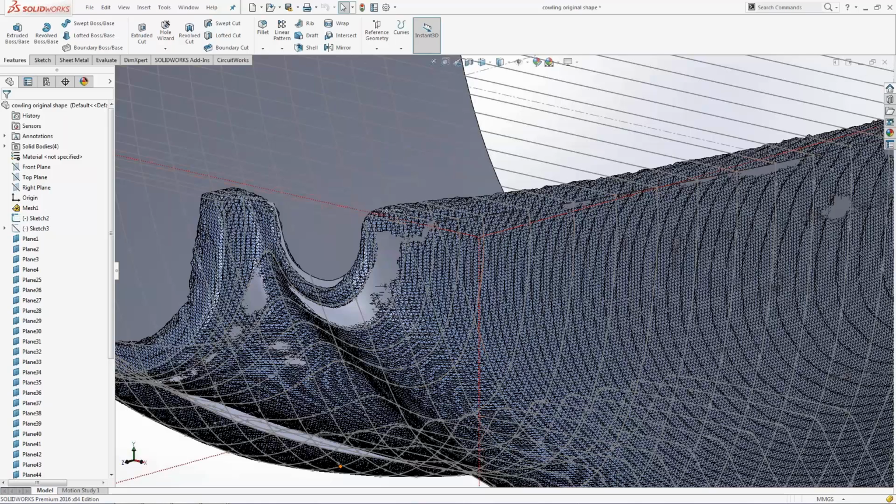And then from that point cloud, we wrap surfaces, or in this case, I've got some cross-sectional geometry you can see here. We just take that scan data, and it doesn't have to be perfect. You can see we missed a few spots, but all in all, we got what we needed out of it. So we were able to scan the cowling and bring the point cloud in.